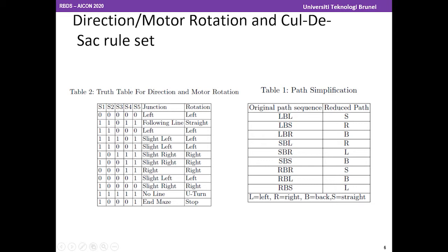So for example, when you do a left, back, and left, which means the left turn is a dead end, so the next time the robot should go straight. And for example, if this is left, back, and straight, which means the robot has to turn right instead this time. Don't go to the left. So this is the reverse path back to the original location.